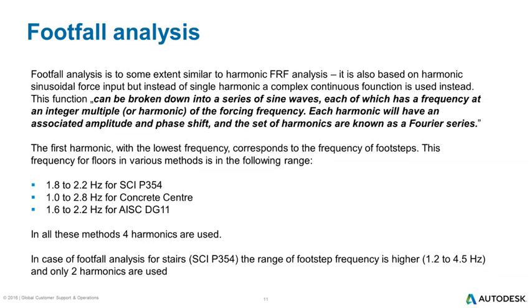Each harmonic will have an associated amplitude and phase shift, and the set of harmonics is known as a Fourier series. One may say that footsteps are composed of several harmonics with increasing frequencies. In general, the first harmonic with the lowest frequency corresponds to the frequency of footsteps, with ranges being defined in the given code as shown on the currently displayed slide. A similar approach is used for stairs.